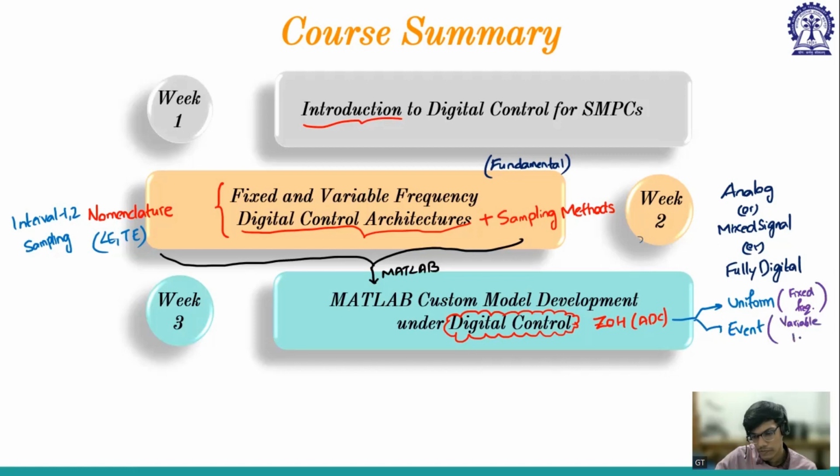As we are taking one sample per cycle and the frequency is varied, the event will occur only once in a cycle. If you take uniform sampling, either we could be taking more samples per cycle, or maybe one sample for a few cycles, which is again not uniform. It should be synchronized with the clock. So that's why we are doing the event synchronized clock.